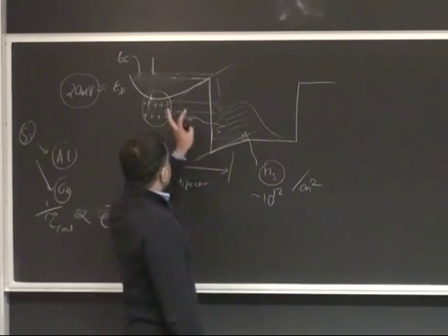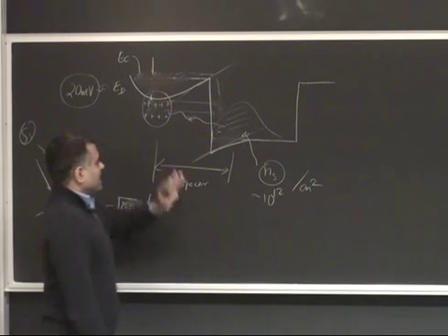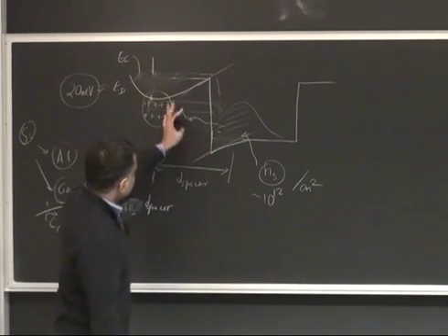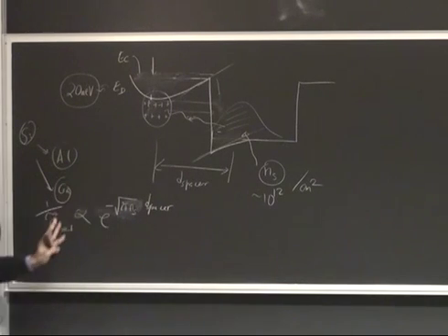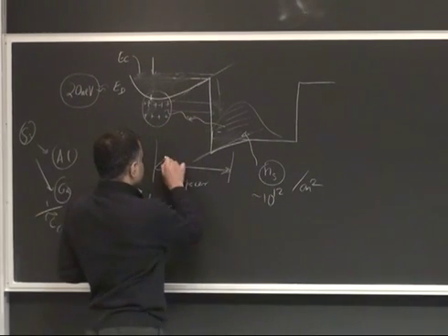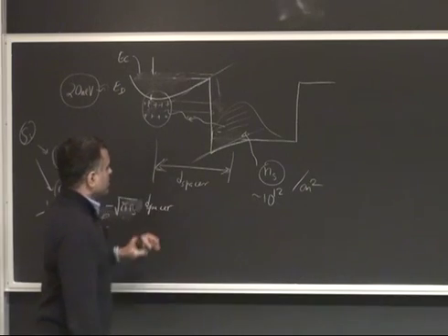Okay? And then that's kind of the reason you get a higher mobility than normal structures. But the truth of the matter is that at room temperature, ionized impurity scattering is not the dominant one. The dominant one is just polar optical phonon scattering. We are going to discuss some aspects of this transport at a later part. Right now, we're going to just look at the electrostatics of the problem. How does this happen?